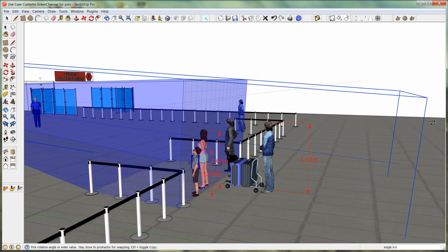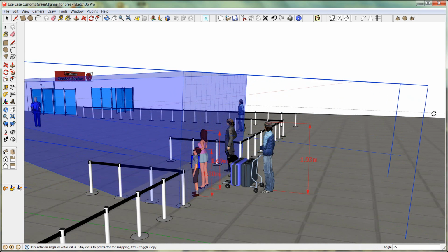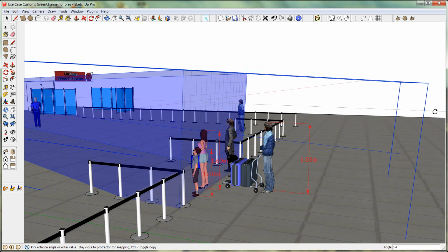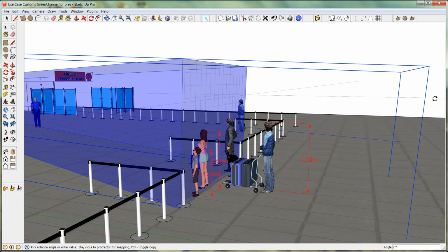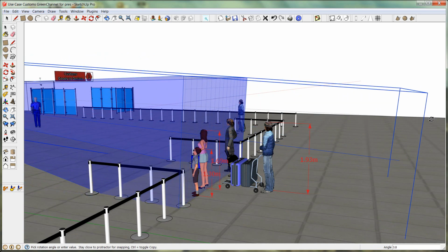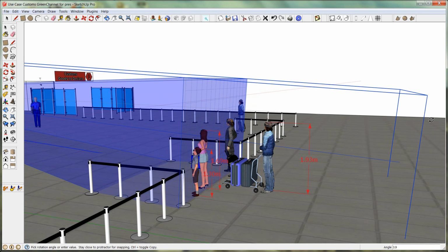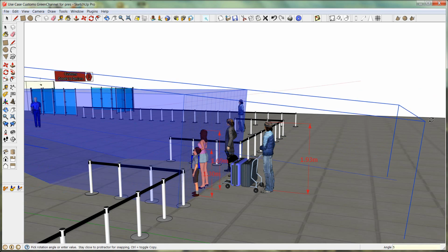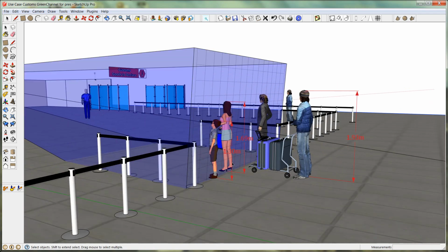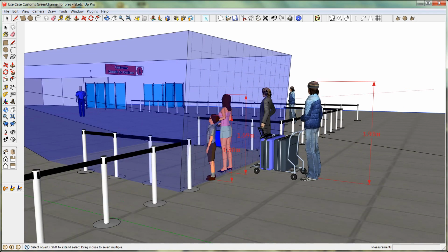Enable the tilting function again, and as you can see, I can move the field of view in the azimuth, positive and negative. If you look down the corner there, it says angle. The angle value is changing. That's the tilt angle. What I'd like to go for is approximately 5 degrees. So I can either run it till it says 5, or I could just enter the value 5, and it'll automatically snap to that number. Why 5? Because then that gives me, remember I needed plus or minus 15 degrees pose, so this is like a preload of like 5 degrees tilt.